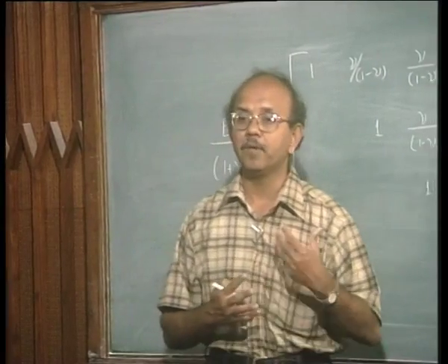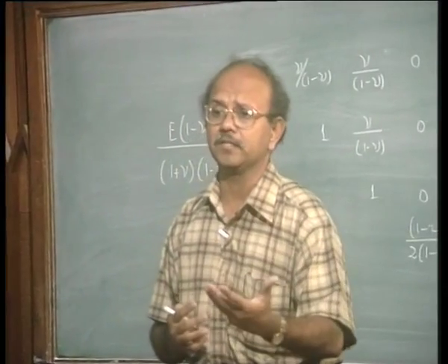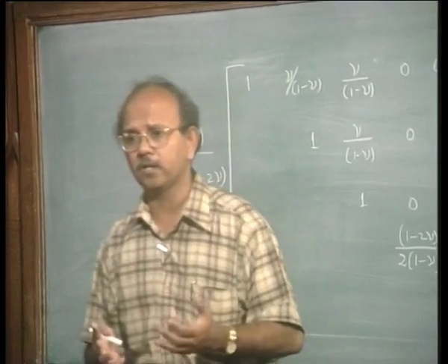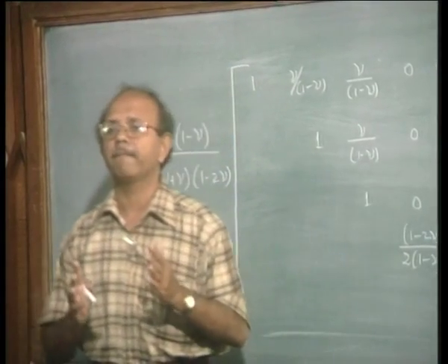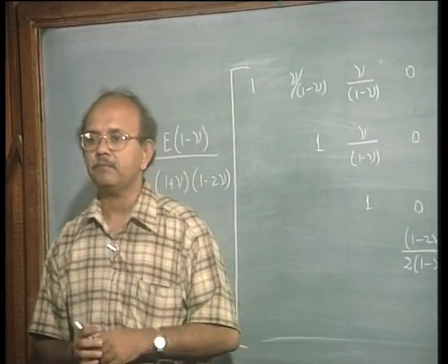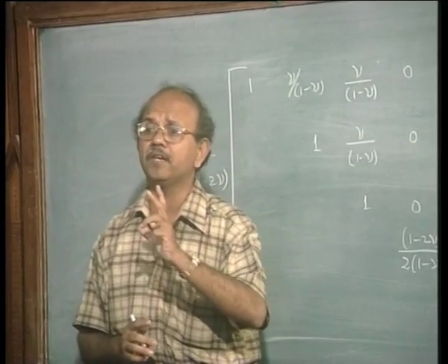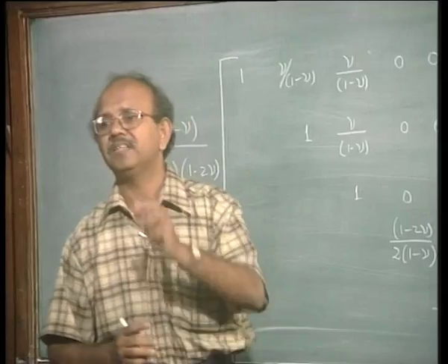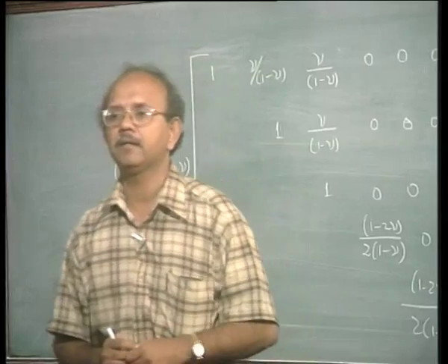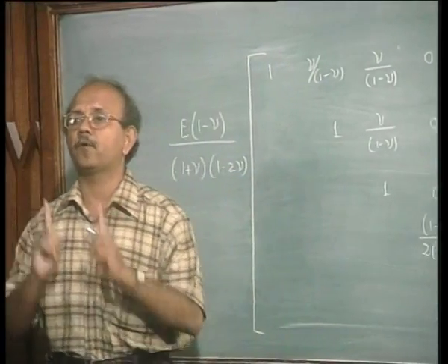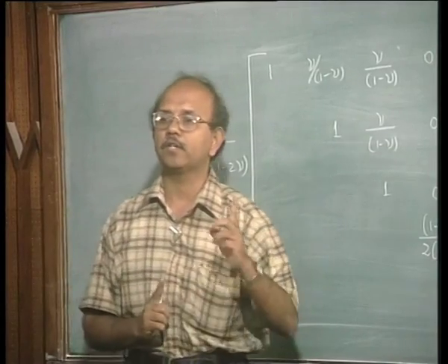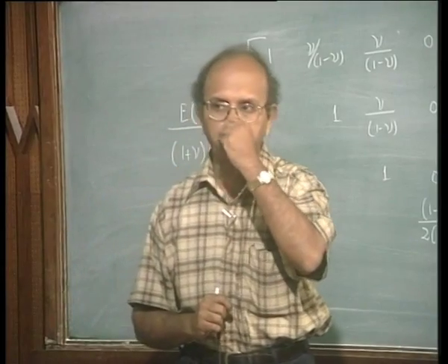In fact, you would introduce errors when you use a solid element, or you have to use a lot more solid elements in order to capture the same effect as what you would see in a beam element. So the behavior need not all the time be a 3-dimensional behavior. That also we will expand as we go along, like what are the problems that you would face if you go to a solid element in order to capture a bending behavior.